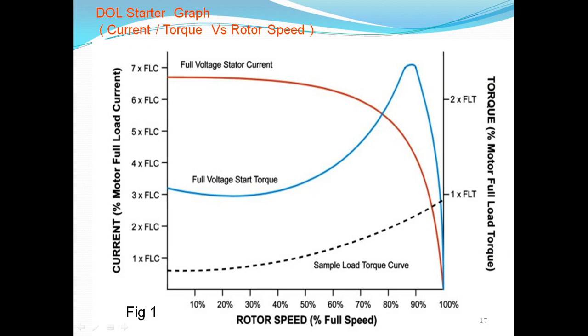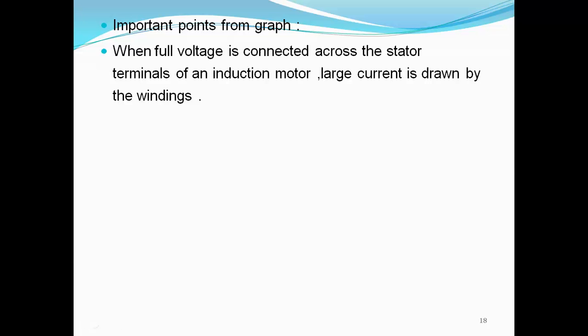This shows the DOL starter curve, that is current versus torque and rotor speed. To draw this, we take the full voltage stator current and full voltage starting torque.